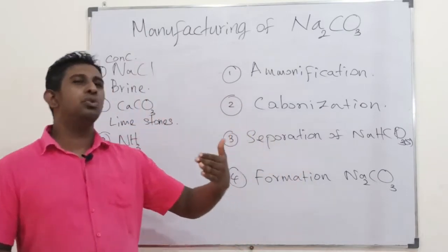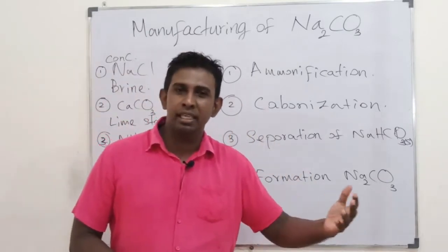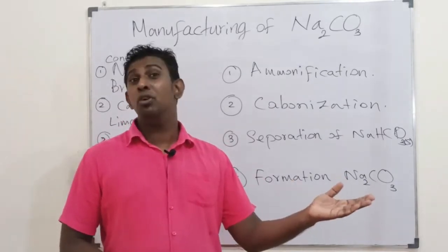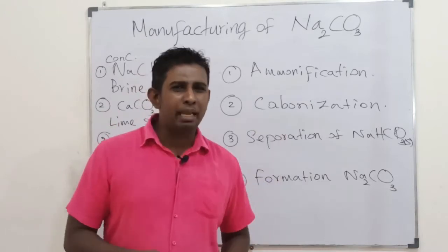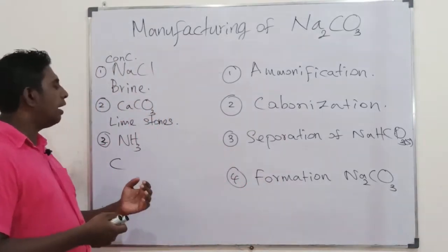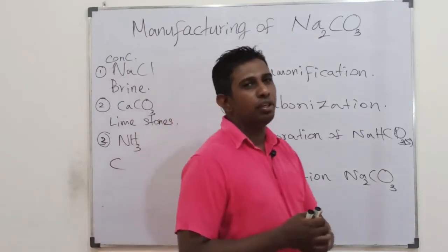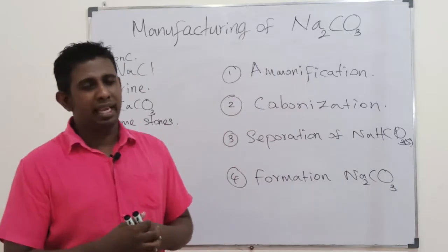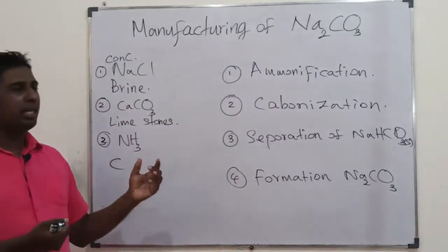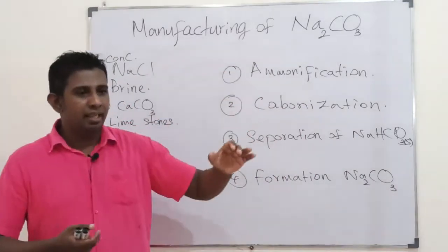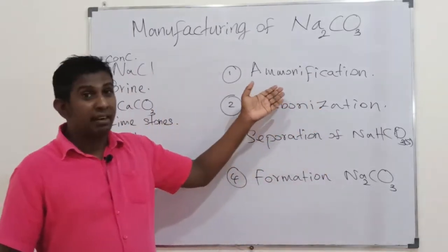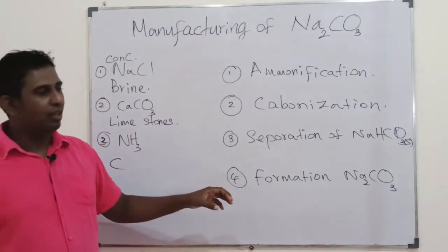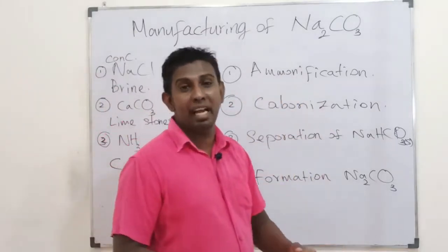Then you could follow further purification steps as well. Students, you would get a byproduct, ammonium chloride. This ammonium chloride byproduct could be used to reform ammonia. We could reform ammonia there. So we could recover that ammonia, which we fed at the very first inside the first tower. We could recover that ammonia at the end from the final solution left behind.